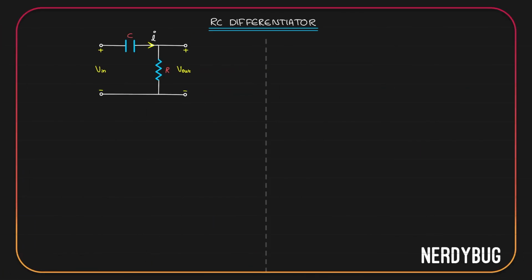Let us take the next circuit. It is the RC differentiator. This is again a simple RC circuit. We have a capacitor of capacitance C. We have a resistor of resistance R. Input is given over here. Output is taken across the resistor. Isn't this the exact circuit for a high-pass filter? Yes, it is. We are going to learn how we can use a high-pass filter as an RC differentiator.